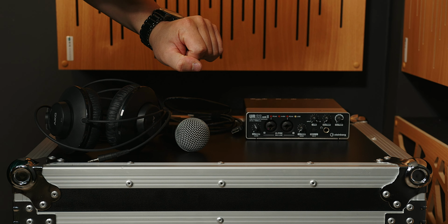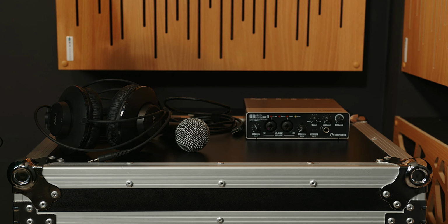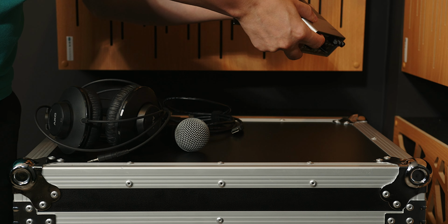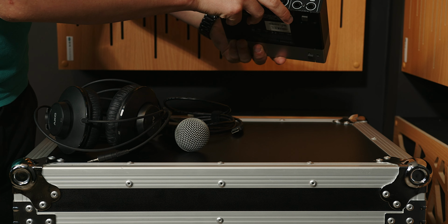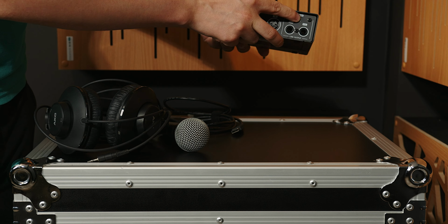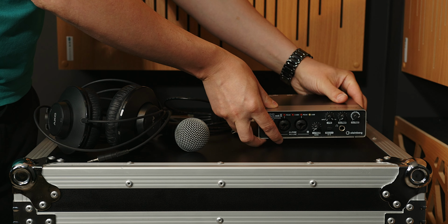Then we've got the 48 volts, so that's called phantom power. Now, that may be confusing to some of you guys, like what the heck is phantom power? So it's basically an extra voltage signal that gets applied once you turn something here in the back. This particular one has a 48 volts button here, and then you can turn that on and off. So what that feature is used for, certain condenser microphones, for example, they require this extra power in order for them to be driven correctly. Without that power, the condenser microphone will not work.